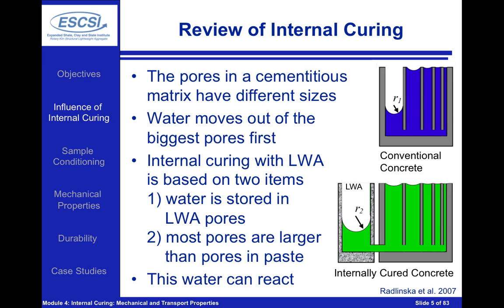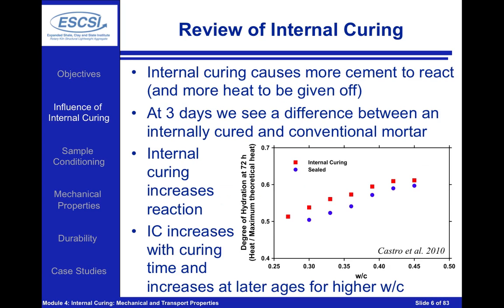This water will then be available that can react with the cementitious material and can hydrate the system further. And this is exactly what we're after. We're after the water moving from the lightweight aggregate into the paste to sustain the hydration reaction. Now you may ask, well, how can we measure this reaction?